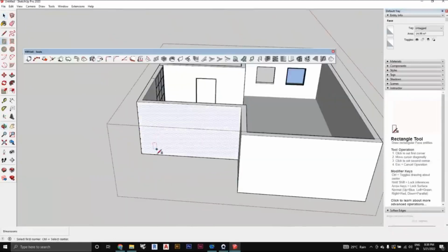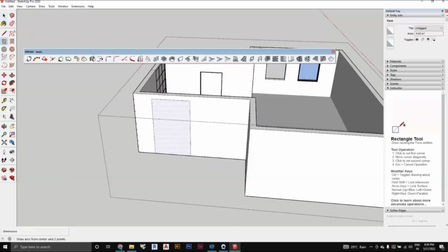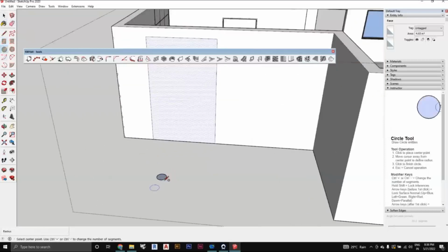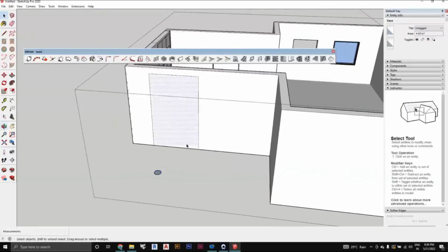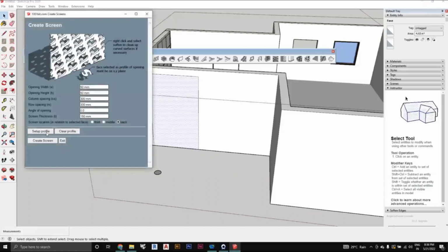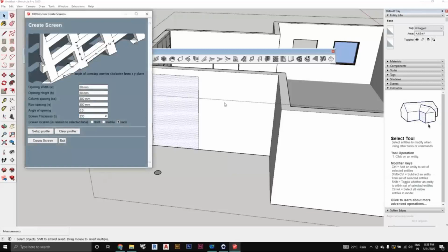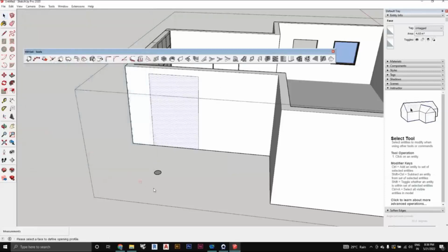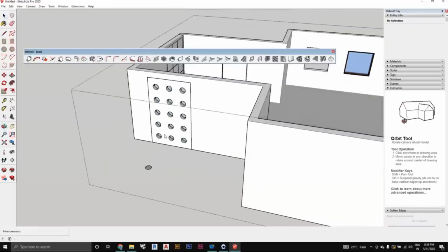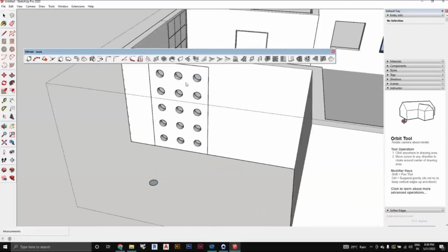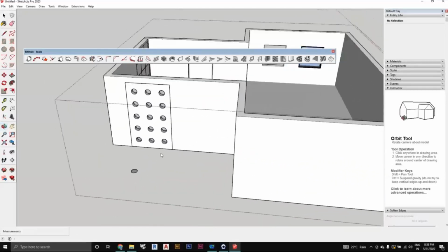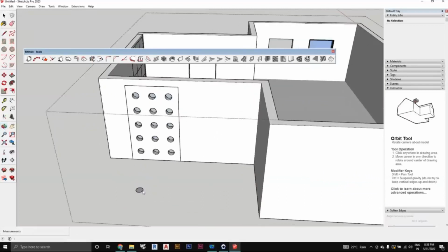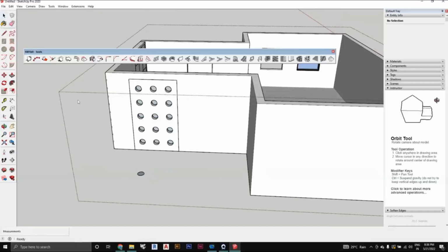Now you can make a rectangle box. I am making a pattern, let it be a circular pattern. I'm not making it too elaborate. Make it a group, and then you need to make a jali of the circle. I just create grills. Then you can go to setup profile out here. Make the screen thickness 230 because the wall thickness is 230. Then go to setup profile and select this. You can see what happened. This circle becomes the pattern. So you can make any different patterns that you like, select on it, and it will create it as well. Cool. Any surface that you have, you can select it, make it, and then just select the profile, and you will get it. Till now, any doubts?